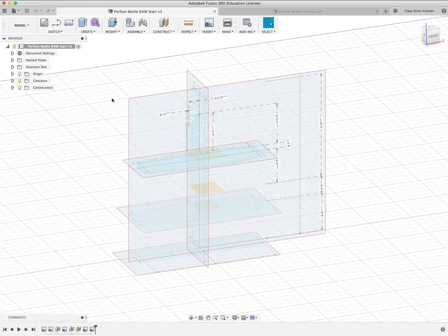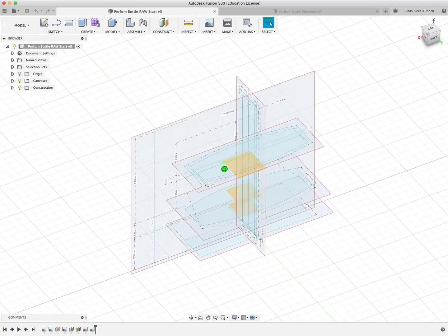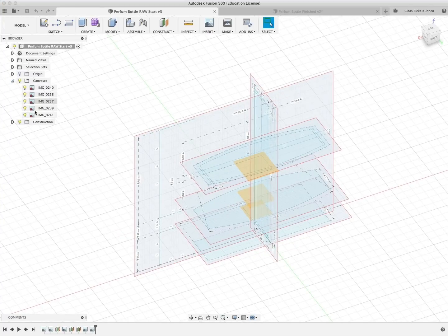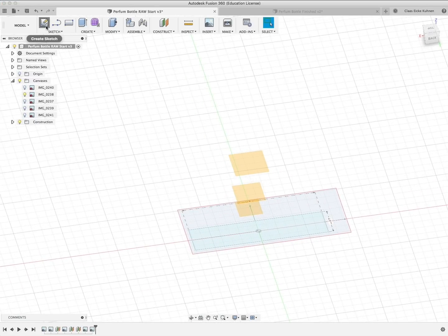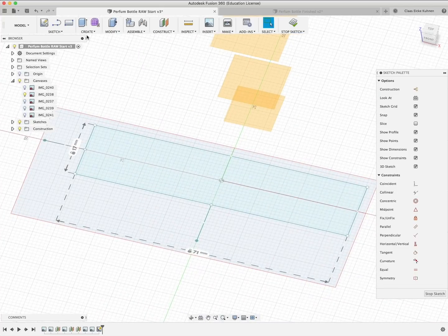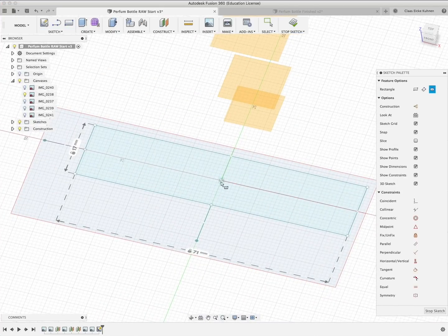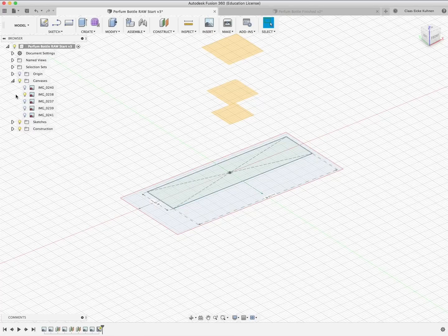So with parametric modeling, when you want to do a sketch, you always have to create a construction plane. Onto that construction plane, we can then put the sketch. Now, this file, also the Shaper file I shared with you, has all the background images in it, so you know exactly the dimensions, etc. I will start with my first sketch, which is on the ground. So I will create a sketch on the ground plane, and I know this is 17 by 71, so I will quickly create a rectangle from the center, 17 by 71. Very good. This is the first sketch I need.